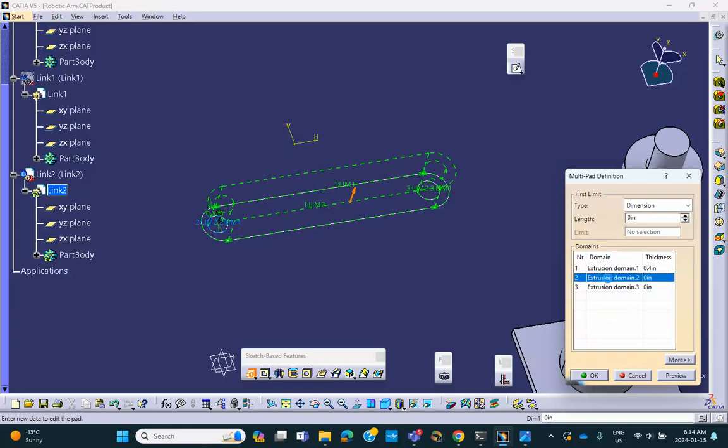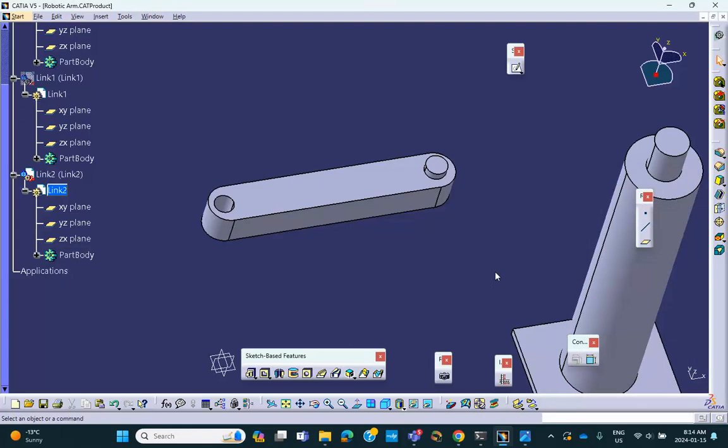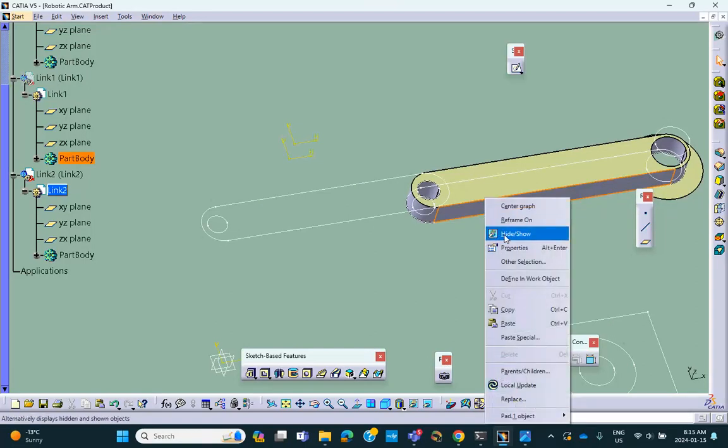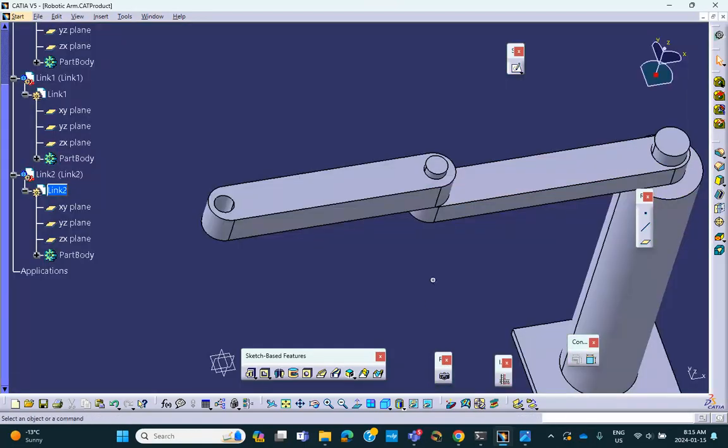All right. This one is the small one on that side. I want it to be a hole, so leave it as 0. And this is the hole on the right side, and I want this thing to be a pin. So let me make this thing 0.5. Obviously, it has to be bigger than 0.4 because otherwise 0.4 will be the same height. I'll make it 0.5. So this is what happened. All right. Where's the other guy that's hiding? So let's get the other guy back. It's right here. Let me bring it into the show mode right there.